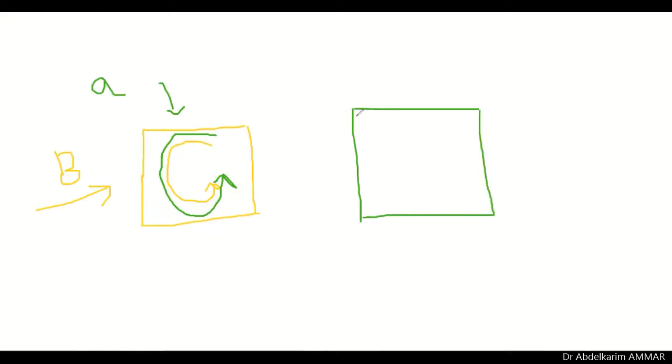If we want to reduce the effect of the eddy current, this core must be divided into thin sheets like this. And between sheet and sheet, we have an isolation material. So if the core is composed of those compacted sheets, the current in these sheets gets reduced like this.